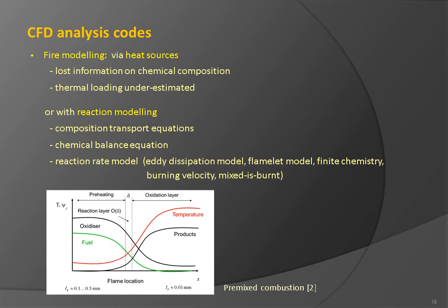Adjacent to the reaction zone is the preheating layer, where the reactants are preheated to the combustible temperatures. Due to its limited thickness, the combustion reaction very much depends on flow conditions, with limited speed and strain to sustain it.